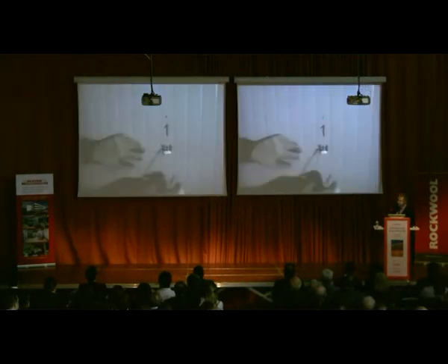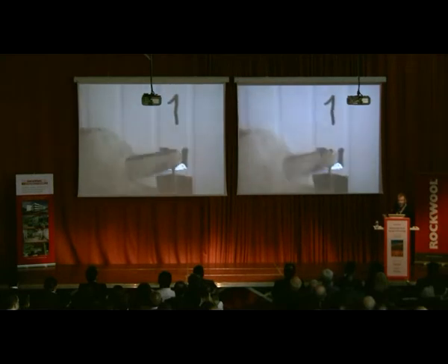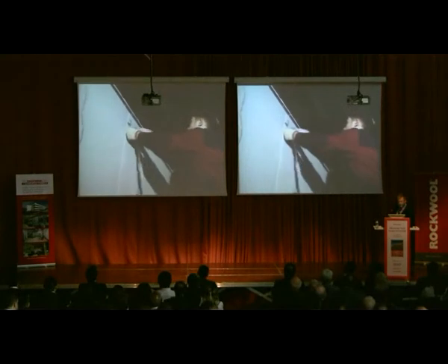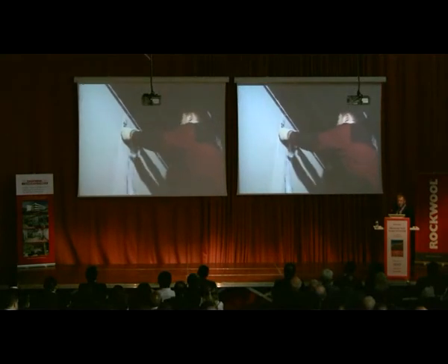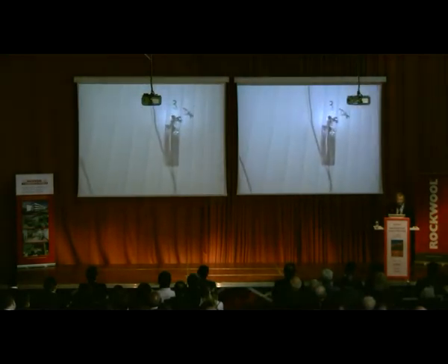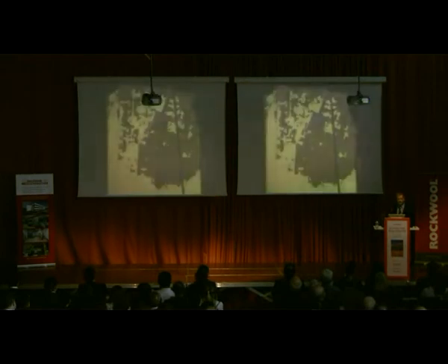So now the laboratory operators are applying thermocouples to measure temperatures on certain points, which are prescribed by the test standard. And sometimes we also measure radiation or heat flux for constructions which are on exterior walls.